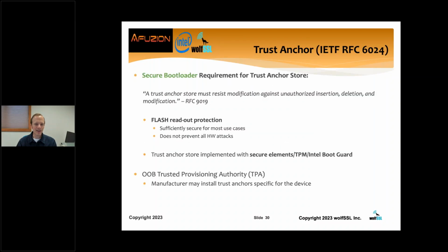So if we take that trust anchor store definition and we look at how it applies to a secure bootloader, well, there's where we can come into play with the RFC 9019, which says a trust anchor store must resist modification against unauthorized insertion, deletion, and modification.